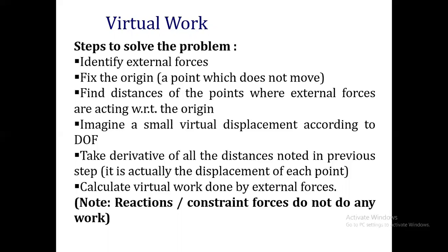So in that process, we compute virtual work done because of each individual external force or external loading. And we apply the principle of virtual work as: the algebraic sum of all the work done will be equal to 0, delta W equals 0. Please keep in mind that support reactions or constraint forces do not contribute towards the virtual work. This is one of the important points which we have to keep in mind.